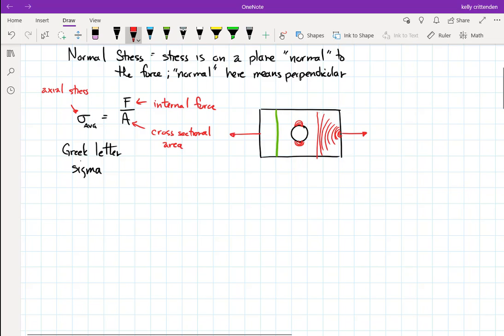At the very end of the quarter, we'll do a little bit of calculation on these peak stresses, these maximum stresses. There are two basic ways you can do that. Either you can put it into a simulator like SolidWorks and have it iteratively solve what these maximum stresses might be, or there's a way to use coefficients that multiply the stress to calculate these peak stresses. They are a thing, and obviously if you don't design for the worst case scenario, the peak stresses, then you may under-design your part. But for now, we're going to calculate these average stresses, the stresses in the bulk material.